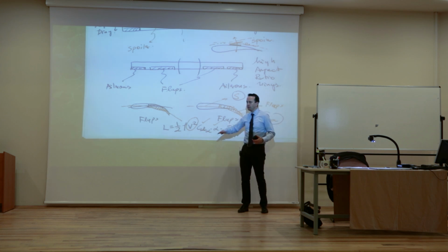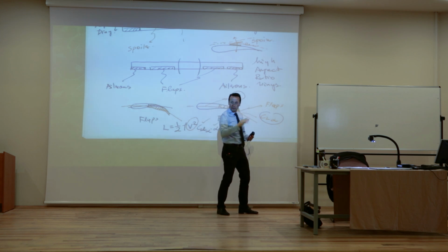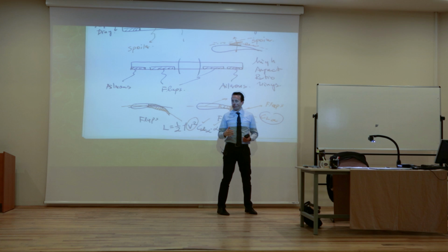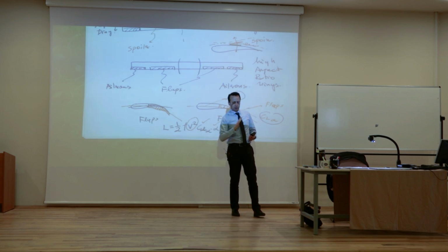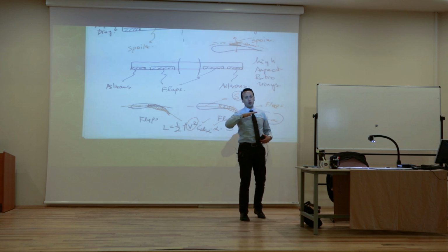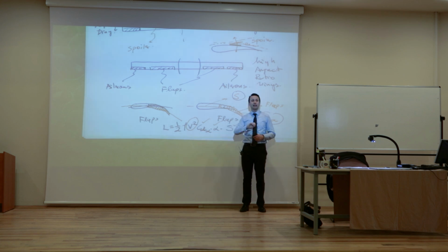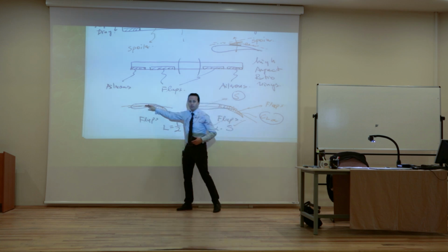You increase alpha, so you see the airplanes landing like that, like that, with a lot of angle of attack, right? But angle of attack has a limit because if it's too large, you go into stall. So you go very close to the stall angle. But then you can increase CL alpha, meaning that you increase the camber, right? And that's what you do with your flaps.